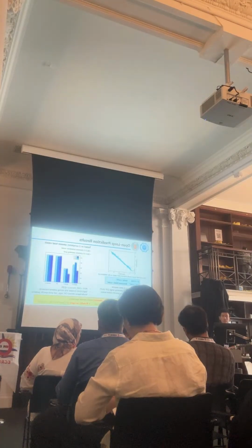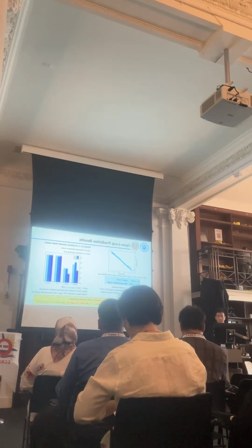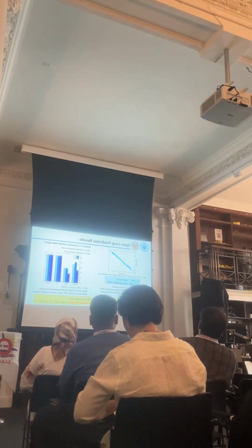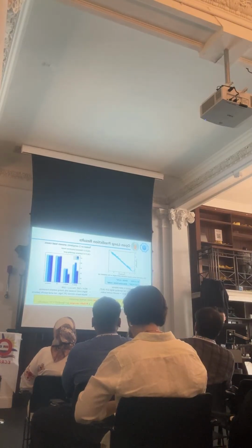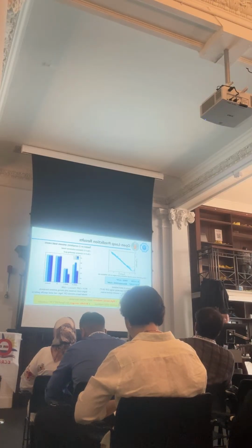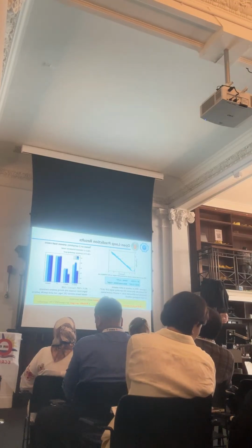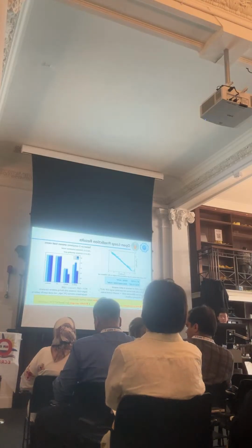So now let's talk about the results, starting with open loop prediction. Based on the independent data set of DLC 1.1, we achieved a great performance here. As you can see from the scatter plot, the predicted pitch angle aligned almost perfectly with the actual pitch across the full operating range from 2.8 to 24.5 degrees. And the extremely low differential RMSE is 0.08 degrees. That means the prediction is really smooth, and there are no high frequency artifacts.